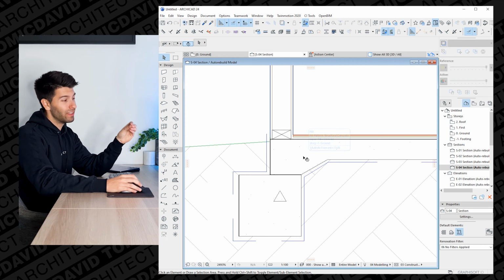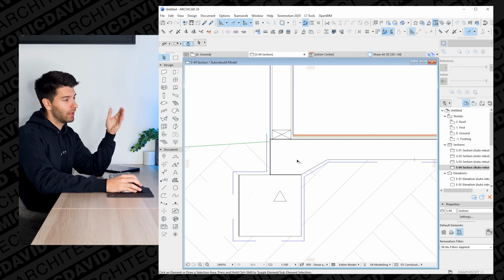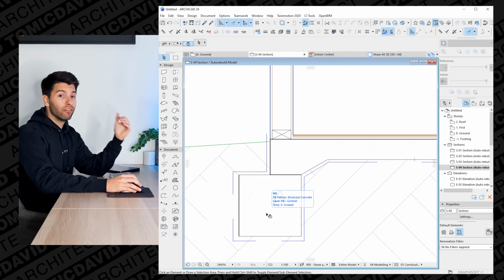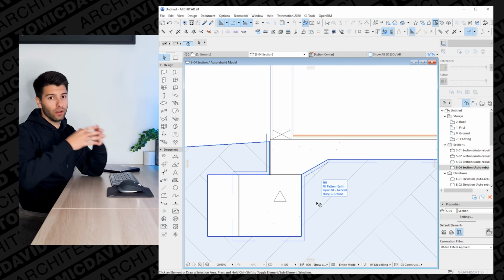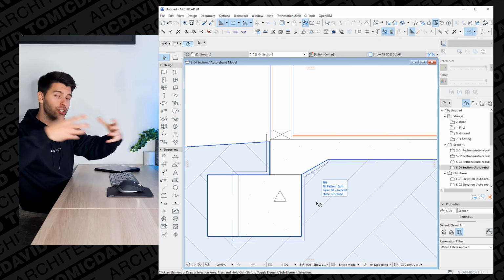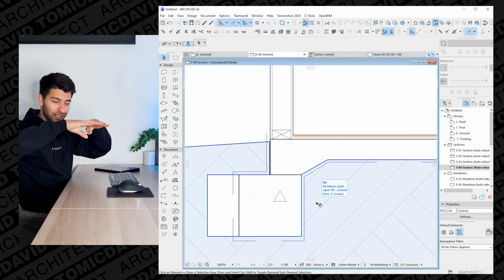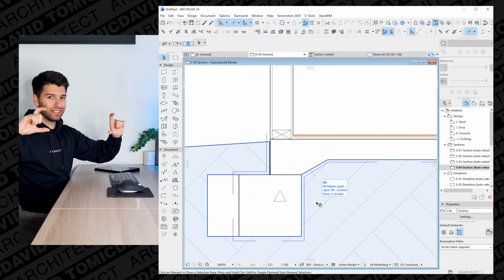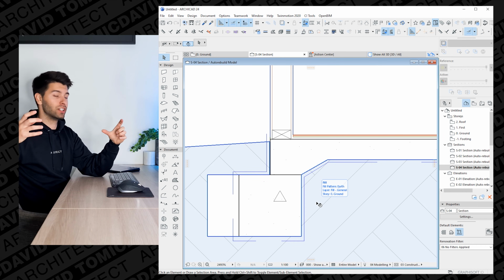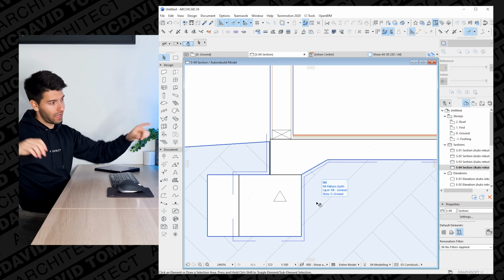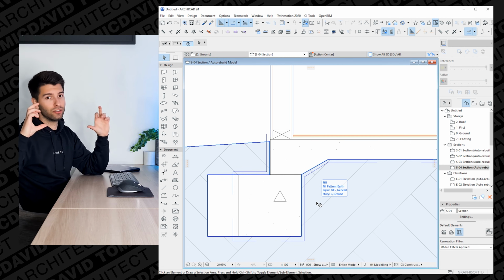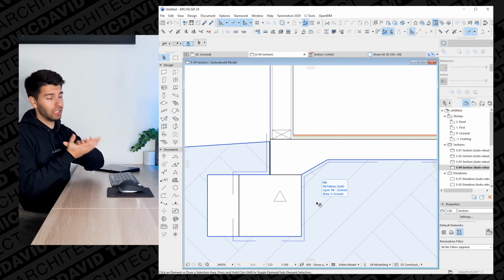However, fundamentally speaking, that is a very simple structural detail for how a timber frame wall sits on top of the edge of a concrete slab, and the concrete slab then sits on a footing itself. This strip footing would wrap around the entire edge of that slab. The slab would be 100 mils throughout consistently, 85 mil depending on the engineer's detail, and then it would thicken out like I've shown in this detail here to the edges to sit on that footing correctly.